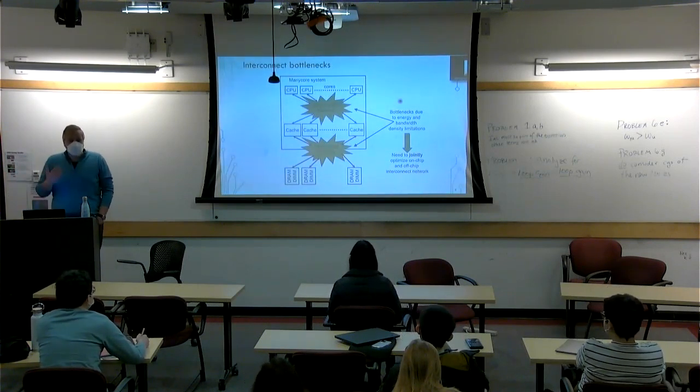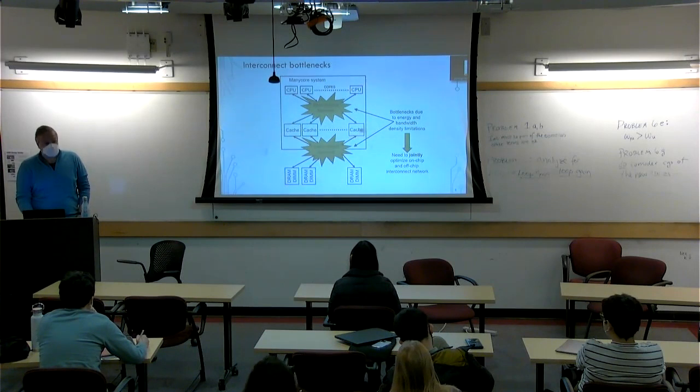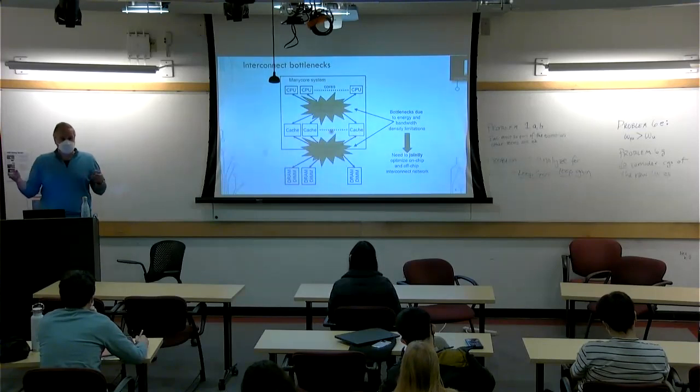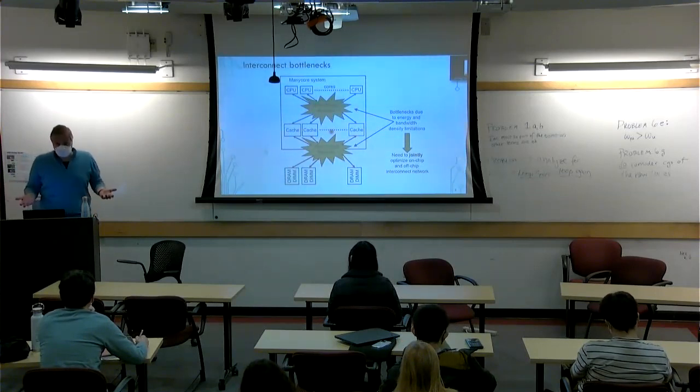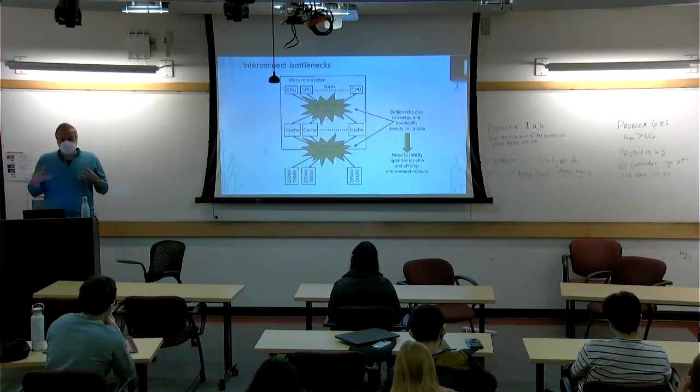Once you start adding more compute units, you have to start thinking about how they interact with each other, right? So what's the interconnect network that connects the CPUs, let's say, and cache on the chip? Is the cache private to every CPU? How do you manage coherency across that? NUMA, non-uniform memory access, is actually really painful to program. You would rather have uniform memory access and big shared memory, but that adds a lot of overhead on the interconnect network, right? People started thinking about how to put all these things together, and that adds a lot of constraints.